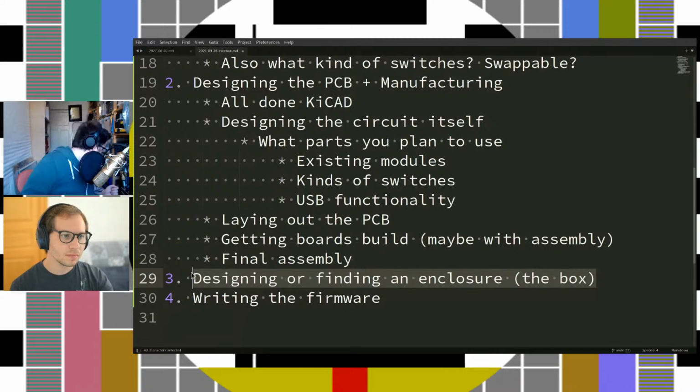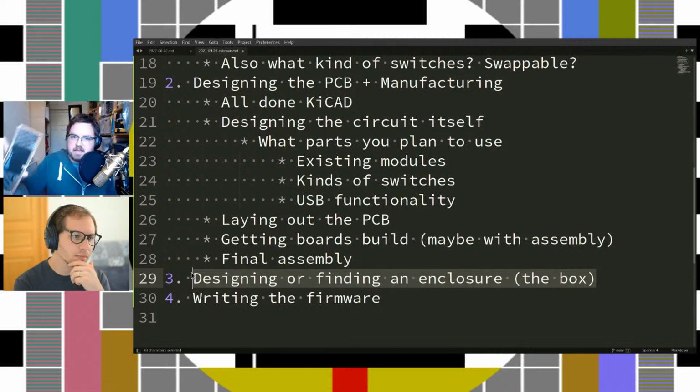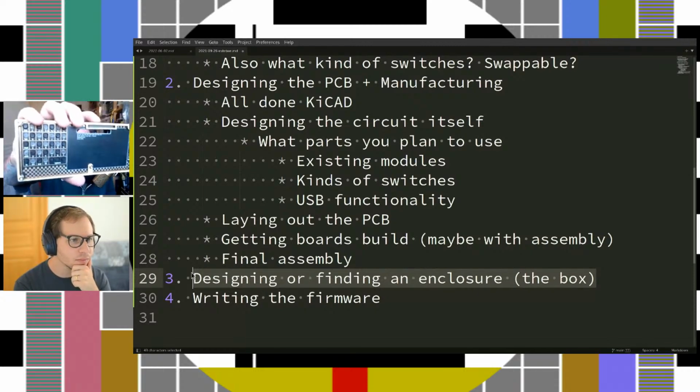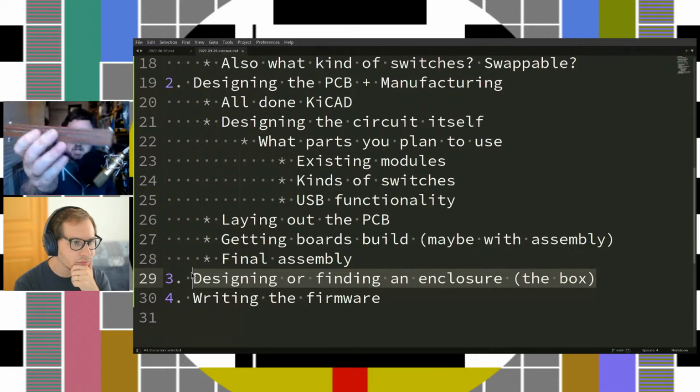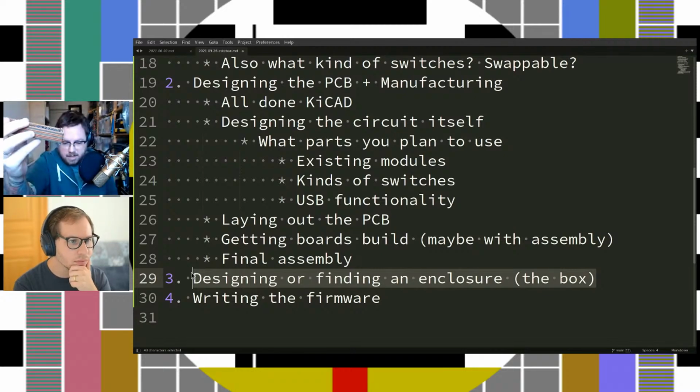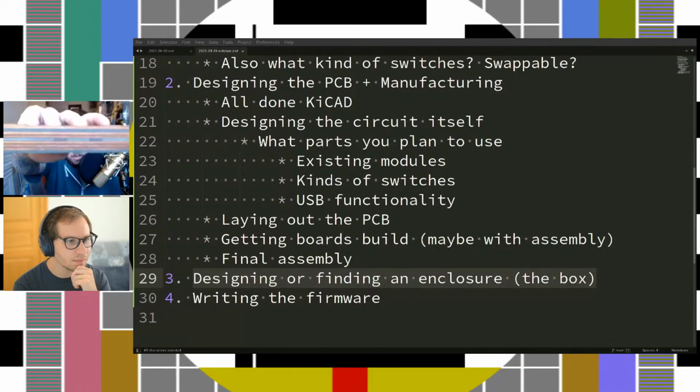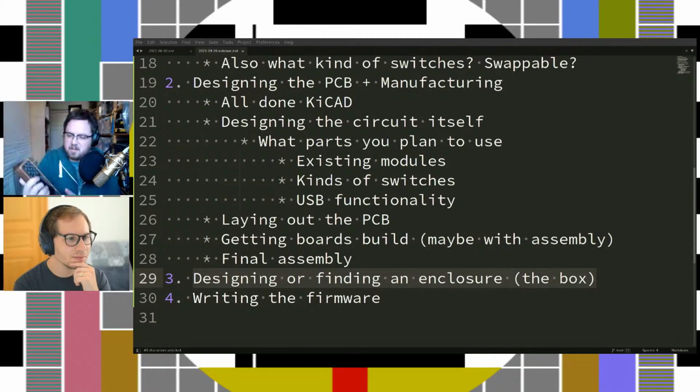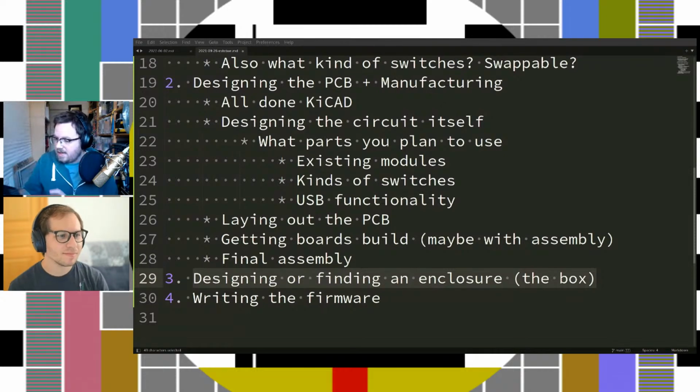Or you can go kind of all out. Like for this board, I ended up doing laser cut wood. There are some websites and services where you can get laser cut wood or plastic and do a much more stack kind of design, where, I don't know, again, how well you can see this, but it's basically just a sandwich of circuit board as a case, wood layer as a spacer, circuit board that actually has parts on it, spacer, circuit board. So there's 3 circuit boards in here, but only one of them actually has components. And the rest of them I just use as fiberglass plates to make nice little enclosures and things like that. Or instead of using circuit boards, you can get wood cut or plastic cut. I haven't gotten into 3D CAD, so I've never made a 3D printer design, but there's a lot of stuff out there for that.